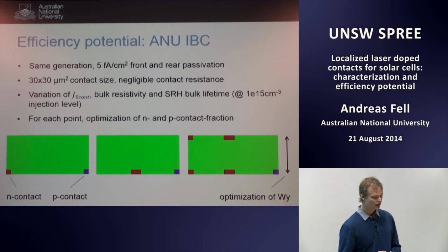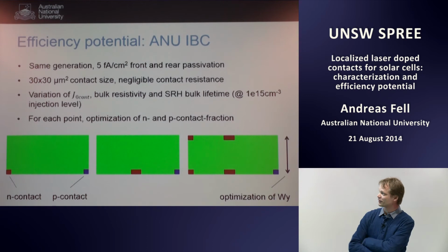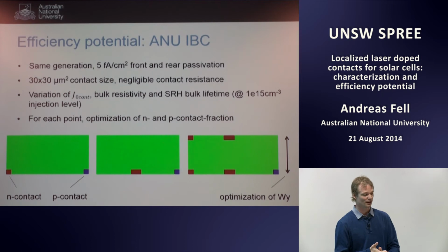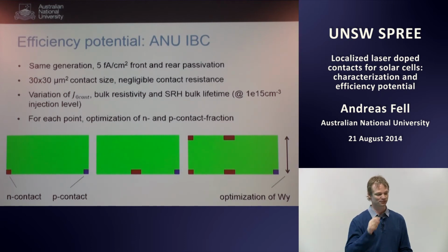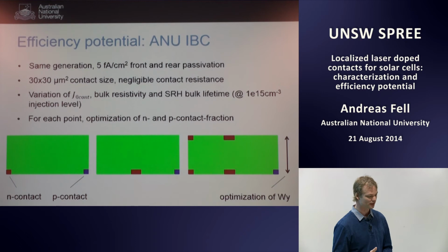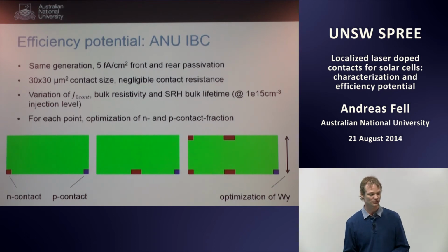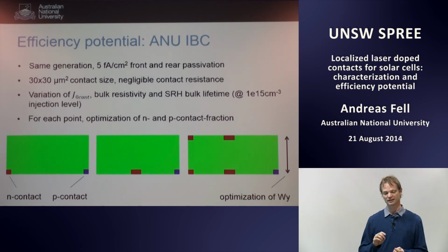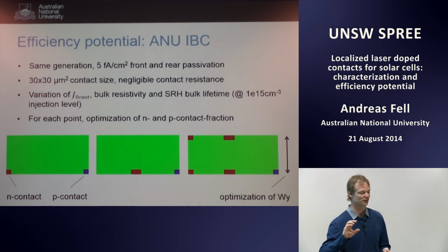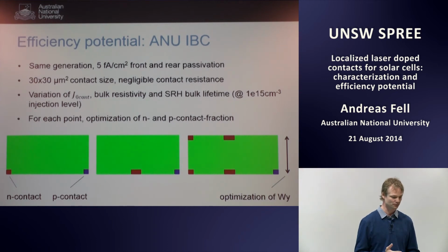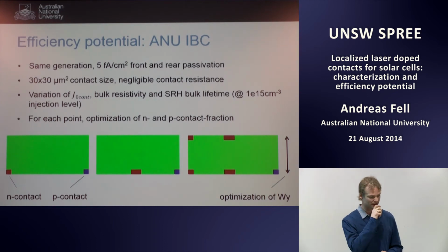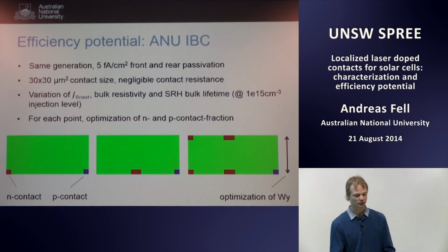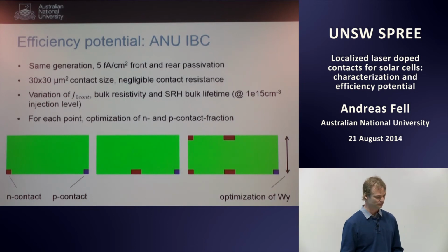at an intrinsic limit. And there's one point about varying the bulk lifetime which is important to understand. We do not just set a fixed bulk lifetime; I will quote some bulk lifetime values, and they actually assume Shockley-Read-Hall recombination. So there's mid-gap Shockley-Read-Hall recombination, so that they reproduce some sensible injection behavior of the bulk lifetime. And the quoted values are representative of the effective bulk lifetime at 1E15 injection level, so what you would measure on the Sinton lifetime tester, for example.